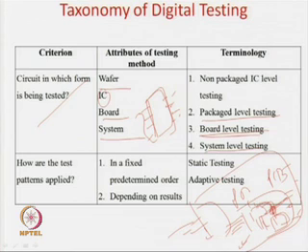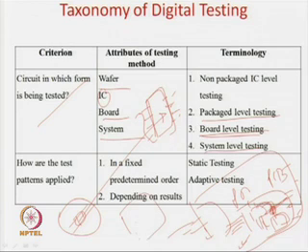Now, there is something called wafer. Wafer is nothing but when the circuit is fabricated, it is a die and inside the die you will have the direct circuit, which is actually put in the IC and then this is packaged. So, directly the wafer can also be tested because it is very easy to get access to all the pins. Like for example, if you have an IC like this, there are lots of gates, only a few of them can be accessed in the pins of the IC. But if you are accessing directly the die, you can access many more pins of it.